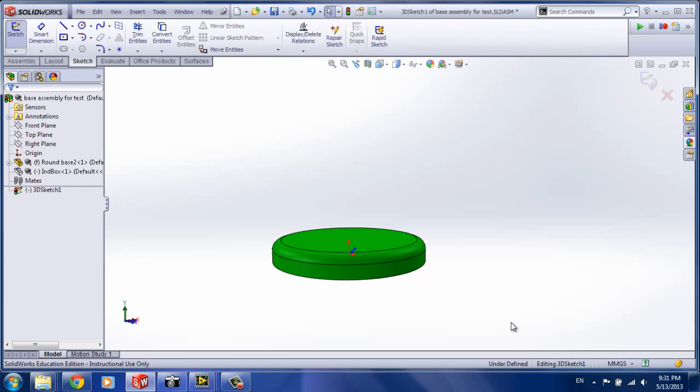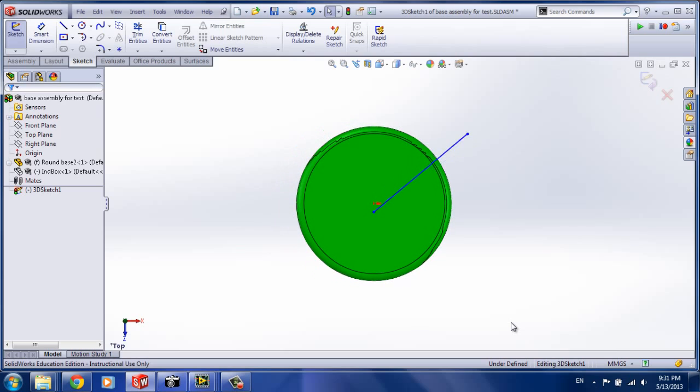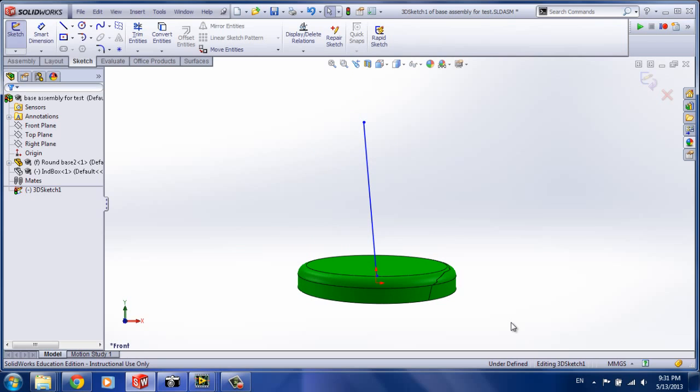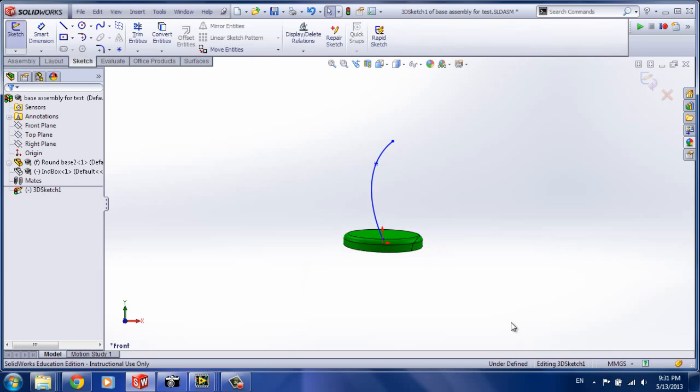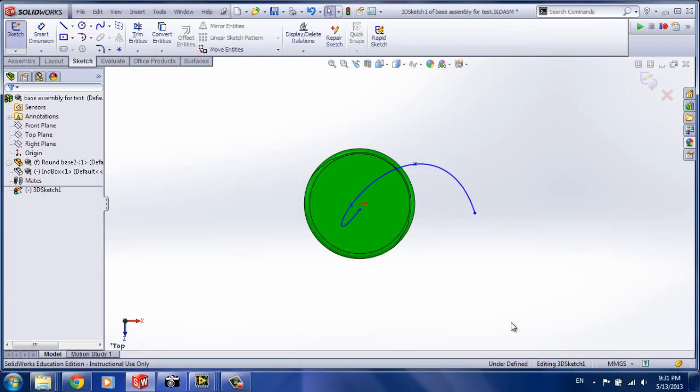Once we initialize the mode, the program automatically creates a startup spline. The first point is fixed to the environment origin. We can control the second endpoint and set it to the desired position. In our program design, we're creating a 3D spline and use the sketch point's 3D coordinates to define the location of the components. In other words, each 3D point represents that there is a component located at that position.